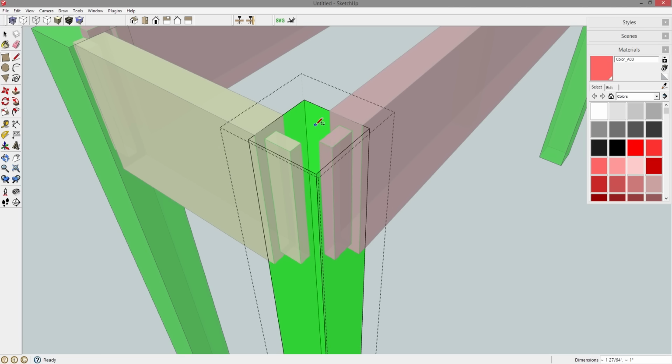So in order to draw on that back face, you need to snap to these object points, or object snaps. So in this case, I'm going to snap to this endpoint over here, pressing R for rectangle, and snap down there.